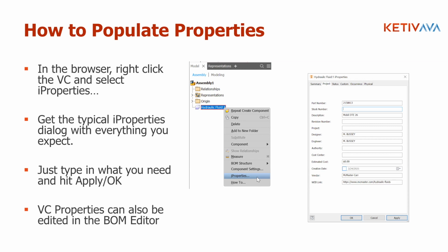Now, part of the reason you can add extra lines on a parts list and you can modify parts lists separate from the bill of materials, there's actually kind of two reasons. The first is legacy. Before Inventor 10, BOM didn't exist in the assembly, and all you had were parts lists on drawings.